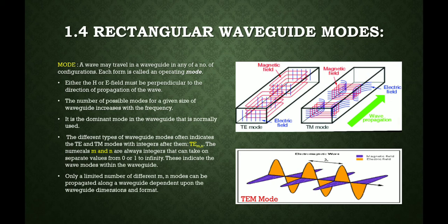Moving on. So what do you mean by mode? By mode, we mean the propagation mode, the path a microwave signal will follow inside a waveguide. So there are different paths possible, but either the magnetic field or the electric field must remain perpendicular to the direction of propagation of the wave.